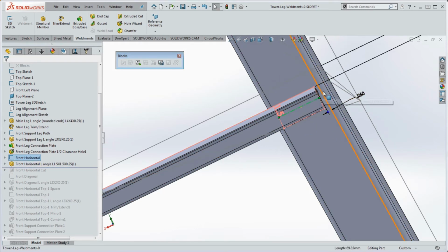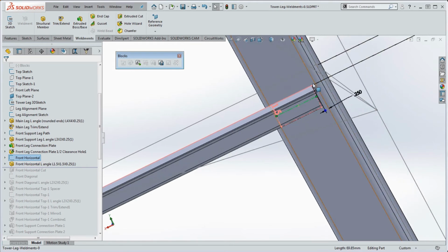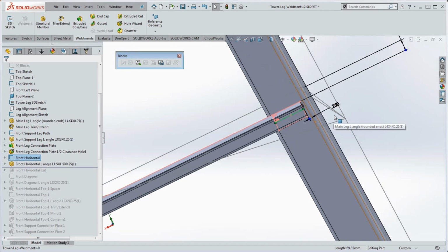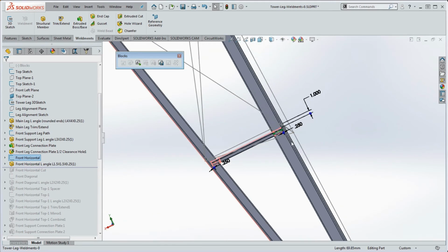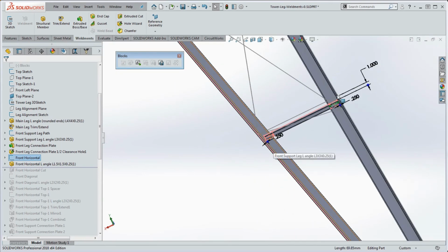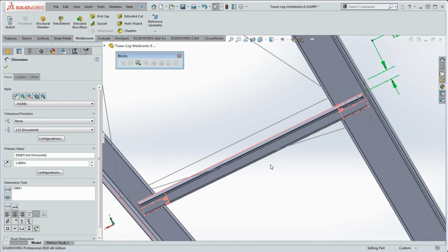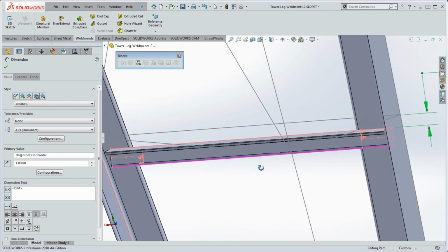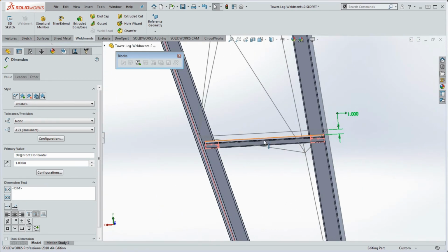So we have a 1/4 inch offset over here between the end of that pass segment line and where that edge is going to be. Kind of like a tangent edge over here where the fillet starts. And then the same thing over here, so that defines the endpoint over here. And then we have this 1-inch dimension, which gives us that relationship with that 3D sketch line that's sitting there in the background. And conceivably, we could have this structural member on the top or bottom of that.